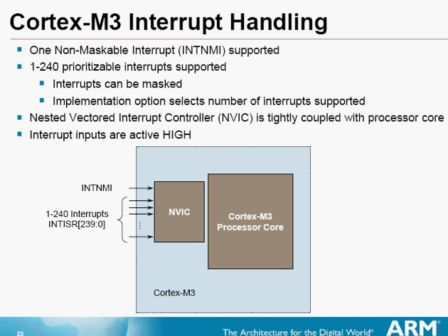Basically, from top level, the interrupts and exceptions are divided into two categories: configurable priorities versus unconfigurable priorities. On Cortex M3, the exceptions and interrupts are divided into two categories based on their priorities: configurable and unconfigurable.